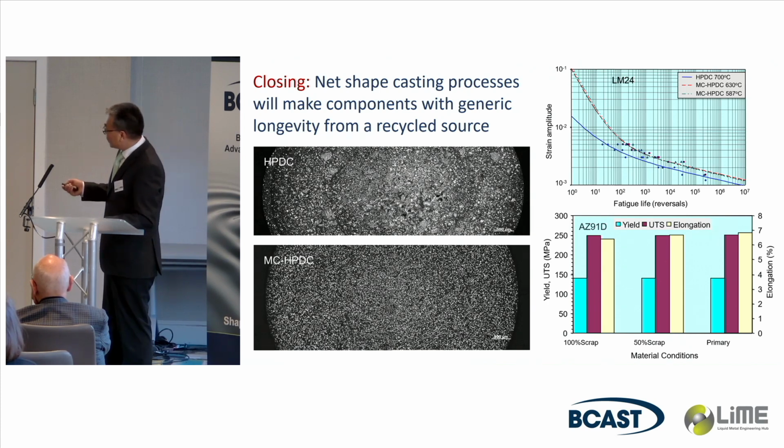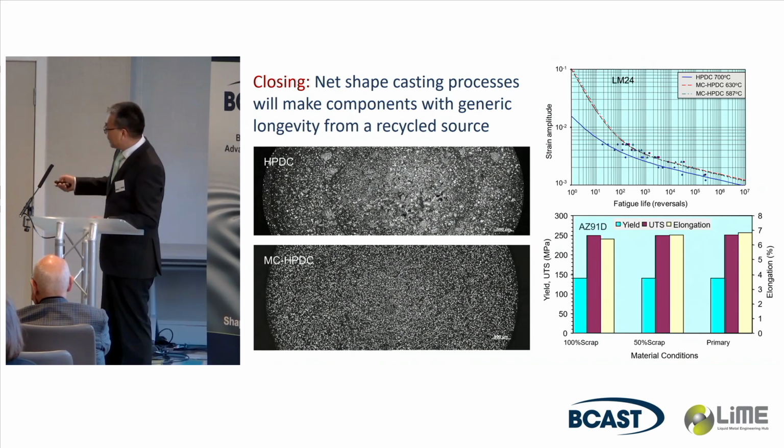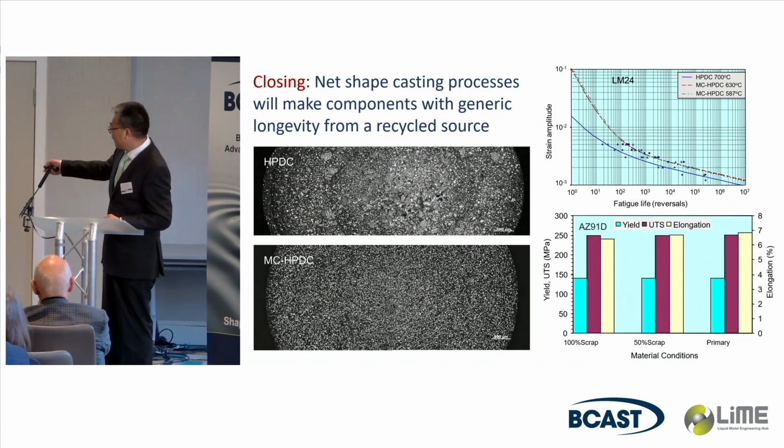And we found out if you use the high shear technology to treat the liquid metal before high pressure die casting, you get this. This is conventional. You have this centralized shrinkage porosity, have the defect bands, have a non-uniform structural distribution there, and you can produce this if you control the temperature and process right. Okay, and what I'm showing here is the real component, a tensile test piece, 6 millimeter diameter.